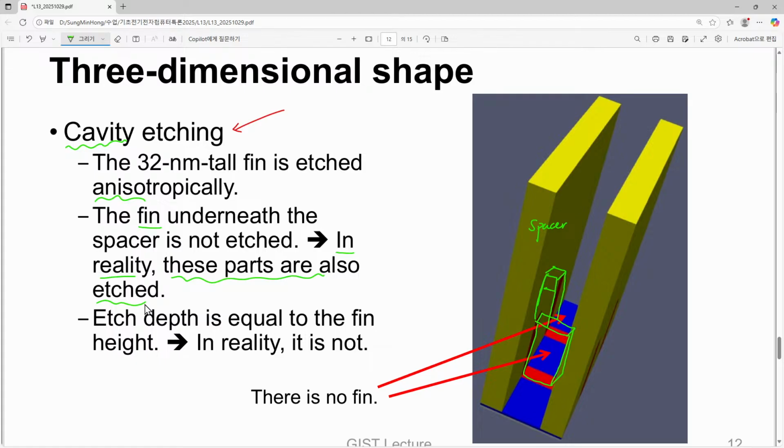Please note that the reason why we do this is closely related with silicon germanium growth, especially in the case of our PMOSFET. This selective growth of silicon germanium, not pure silicon, is quite important because this silicon germanium layer provides certain compressive stress to our channel. Where can you find the channel?